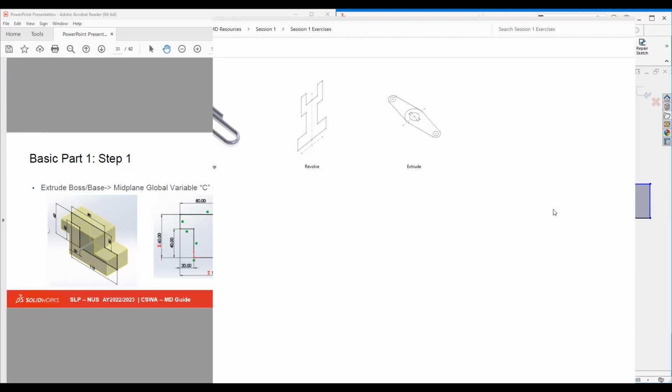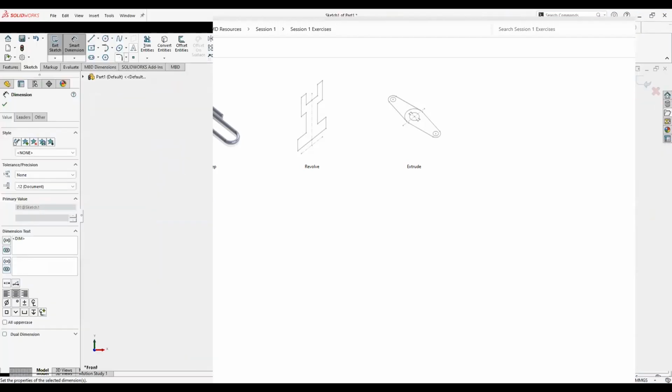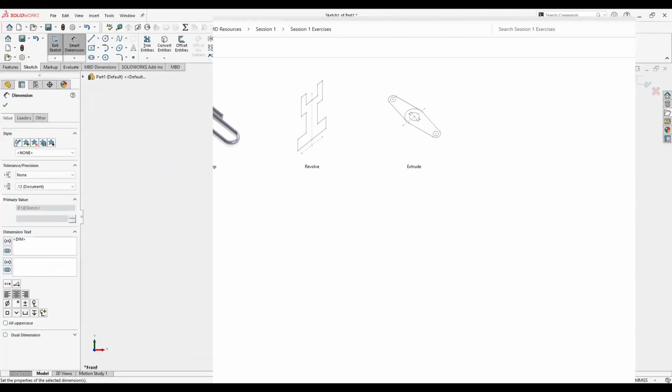Okay. So what's going on is SolidWorks is a highly customizable tool. I'll just make it full screen. All these functions and the layout we can actually customize. So on this top menu you can move your cursor to this tab, or anywhere along the top. You right click, and you will see this menu. The last one is called customize. So you open customize.